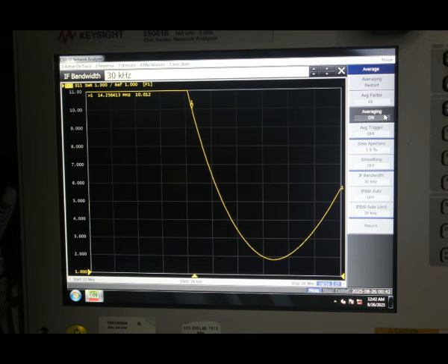That means when we connect the 25 feet of LMR 400, it's going to be on 20 meters, dumping into a 10-to-1 standing wave ratio load, just as if we had a 10-to-1 SWR on the antenna. The only trick is we can measure the actual power that makes it past the mismatch into the antenna.